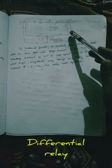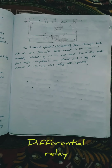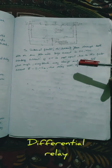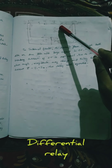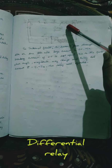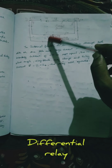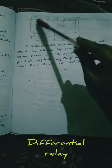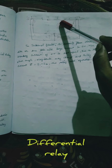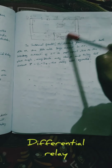Next, if the fault is internal, inside the zone, then the relay should operate. As I mentioned, the fault is inside the zone to be protected. In this case the current flowing automatically alters, which means the current on the fault side goes in reverse.